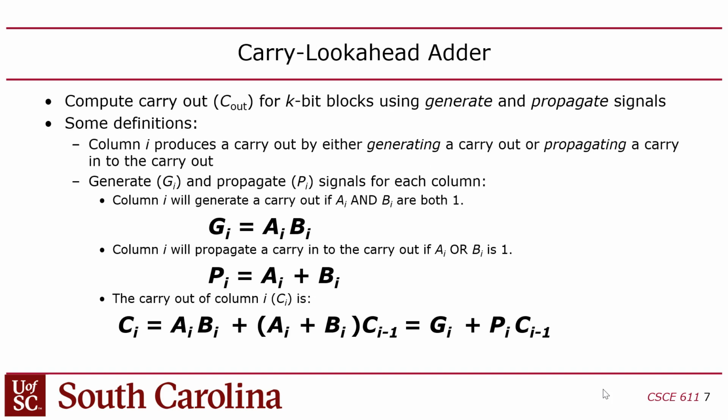So a faster way to do this is using a carry-lookahead adder, and the goal here is to be able to break that long chain of carries. The way you do that is you generate a signal called propagate and a signal called generate from each of the full adders. And then you can infer what the carry-in is into each column from the propagate and the generate signals from the previous columns. You guys with me? Right? So the way you do that is